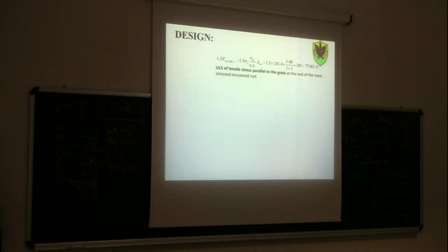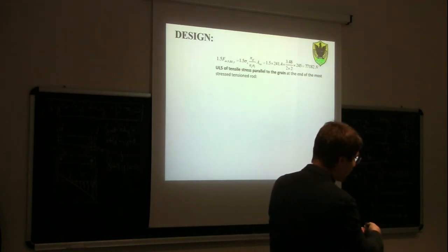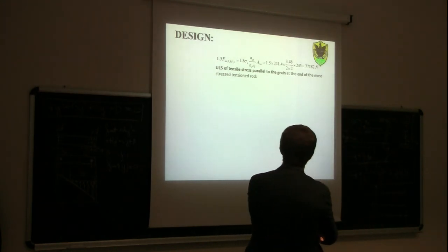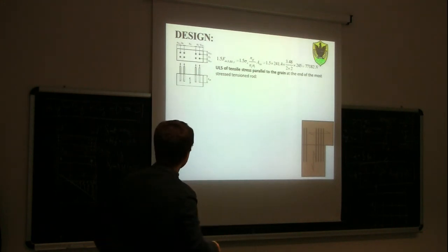So basically we have taken the actual force and multiplied it by 1.5 to make sure that the actual plasticization will always occur before the other two failure mechanisms.